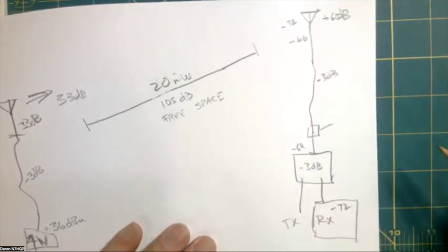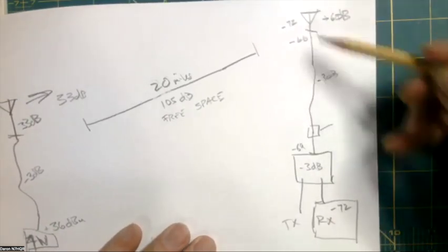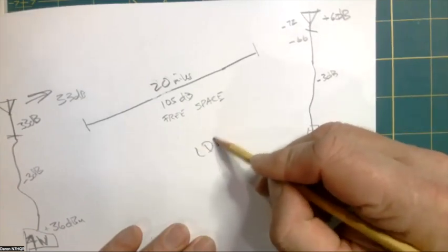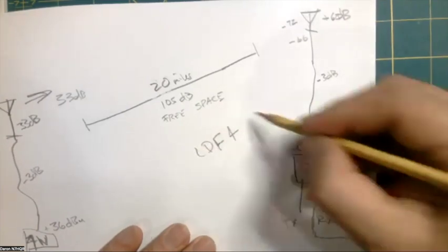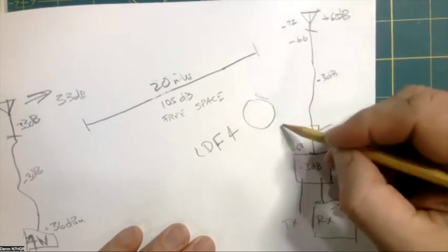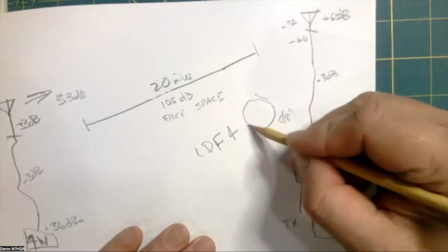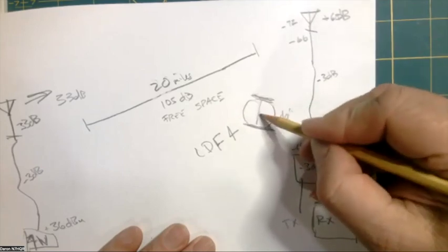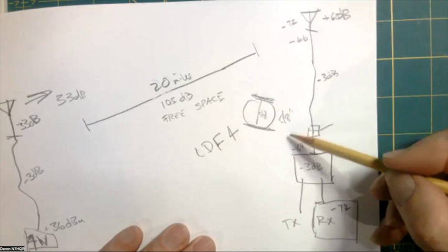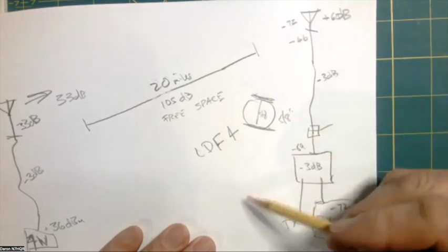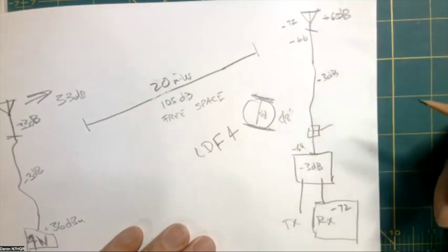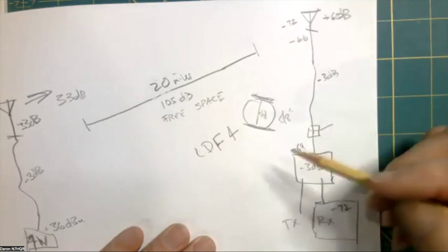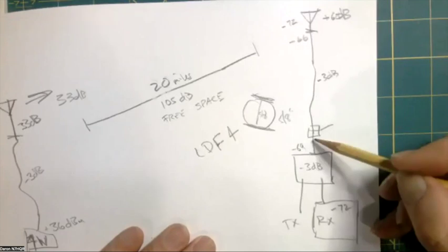Oh, okay, I see. So we would just look up what's called LDF 4, a very common one, which is about 5/8 of an inch on the outside diameter, pretty good sized stuff. It's published what the loss is for every 100 feet of that at 150 megahertz, which is pretty close to what we use. So we would do that calculation.